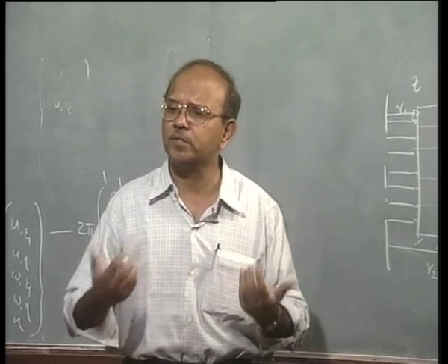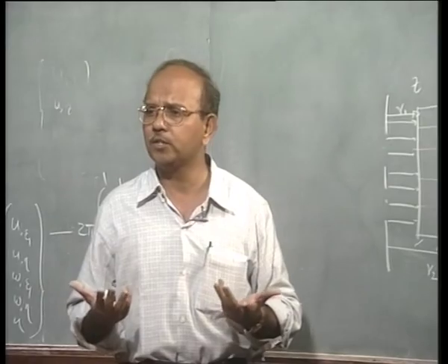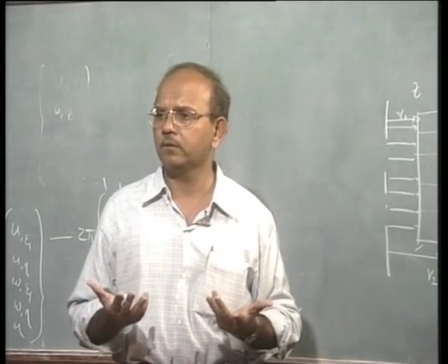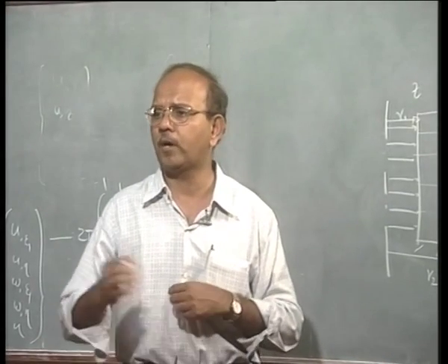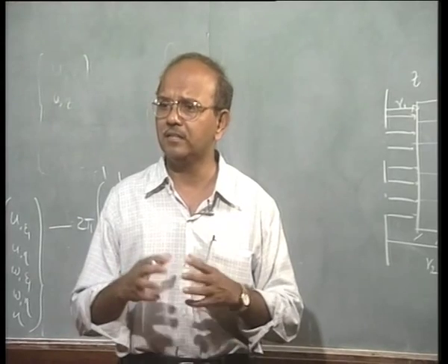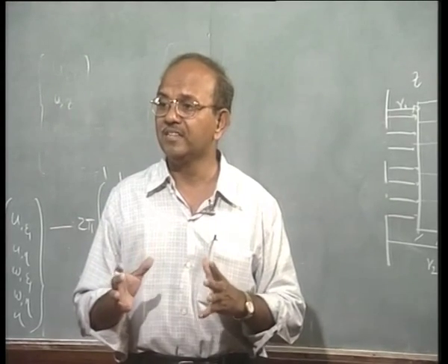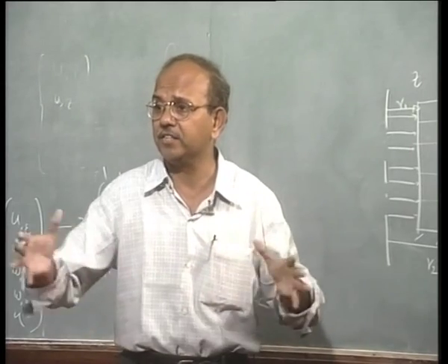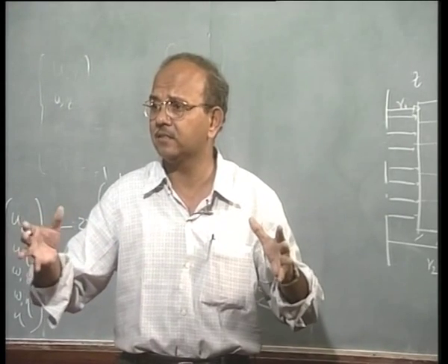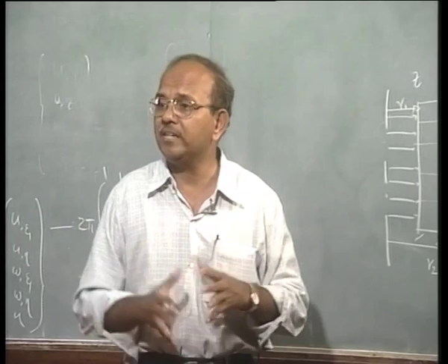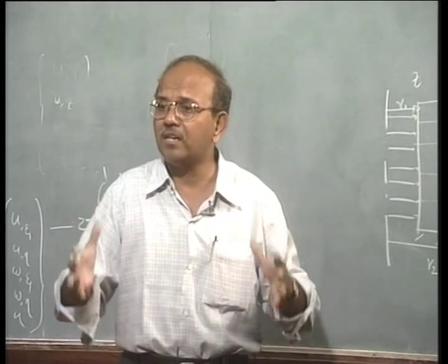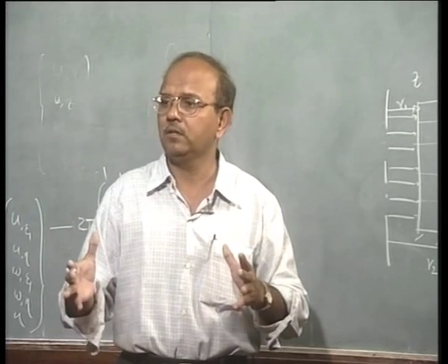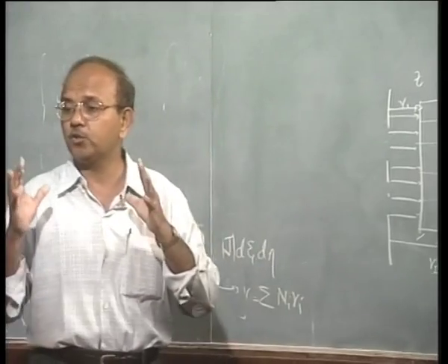After all, why do we want to specify a boundary condition? We want to avoid a rigid body motion, okay. Now if you specify one F and another F, then you do not avoid rigid body motion. In this case you definitely avoid rigid body motion in the R direction, it can't just expand as it likes, okay. The movement in the R direction is not equivalent to a rigid body motion, right. That should be very clear.